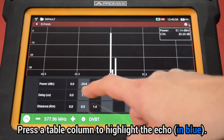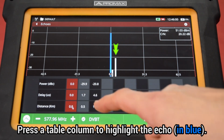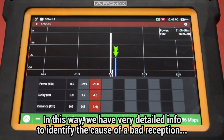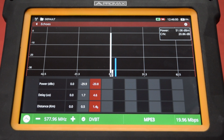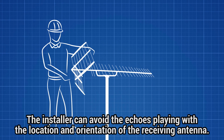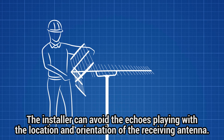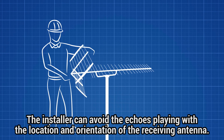Pressing one of the table columns will make the corresponding echo in the graph be highlighted in blue color. In this way, we have very detailed information to identify the cause of a bad signal reception, when other measurements such as power level, carrier to noise, etc. seem to be okay. The installer exposed to these echoes can only play with the location and orientation of the receiving antenna in order to minimize the negative impact that these echoes can have on signal reception.